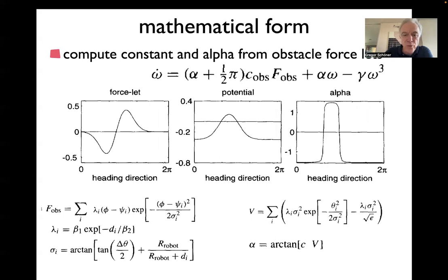So mathematically, we can use the force sets that we're familiar with. This, right? This is from the approach I just reviewed. That is an obstacle force of this form as a repeller in heading direction. And now we need to lift that in terms of derivative. And so what we do is that we use this form to change the sign. So when we're here in this part, we will shift this up. When we're in that part, we will shift it down.